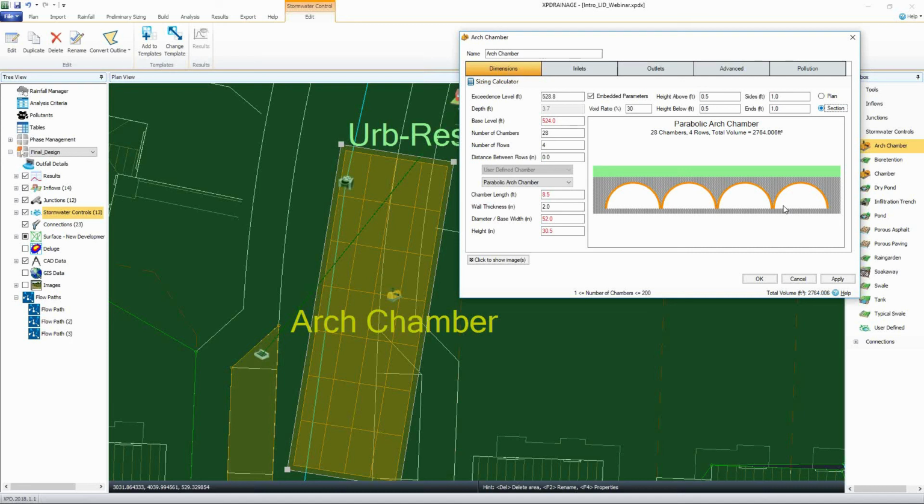It depends, right? So I think of a dry well as being a much smaller structure. And a very, very small structure won't do me a lot of good. That's why they often are very deep. That would be those underground injection wells. And then the deeper you make them, the more likelihood of being in the groundwater table, then you're in trouble. So usually these are much broader, flatter structures versus a deeper, smaller footprint well, if that kind of answers the question.